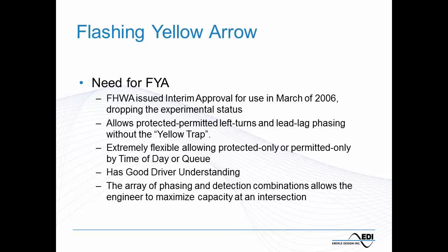The benefits are summarized here. It allows the protected and permissive left turn movements based on whatever the controller decides to sequence it at. It may be due to demand, it may be due to time of day. We can switch from protected to permitted left turns, lead lag, and with the exception of emergency preemption, we do all that without generating the yellow trap.